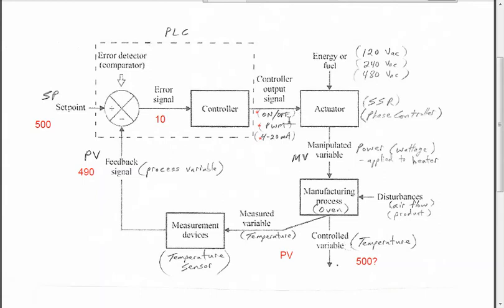So these other types, like I say, we'll get to those, but I could mention, you can probably guess that the farther away you are from the set point, like if the process variable is really far away, you can apply a stronger output signal to the actuator. And as you get close to where you want to be, then the error signal would shrink in size, and in this case, the output signal would get less strong. It would start to back off. Okay.